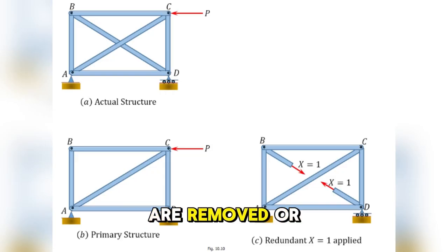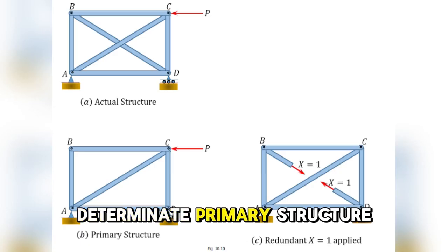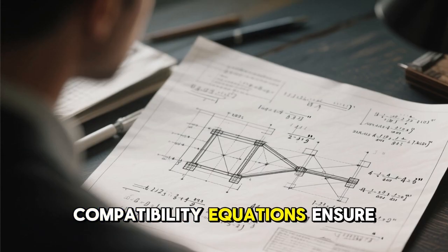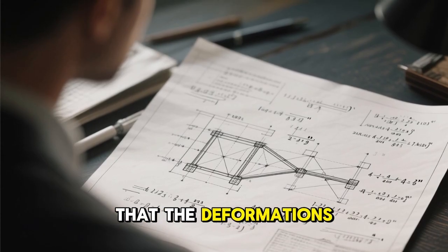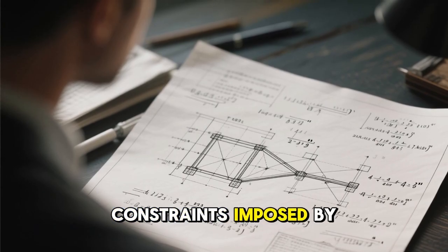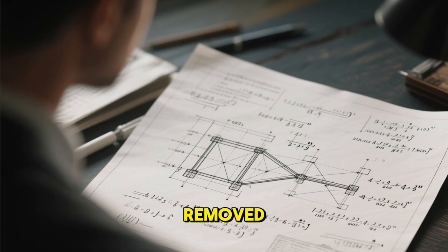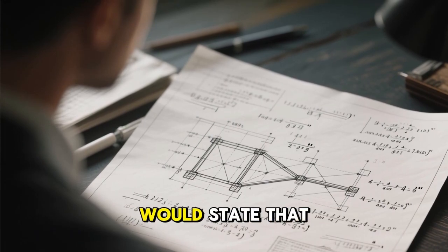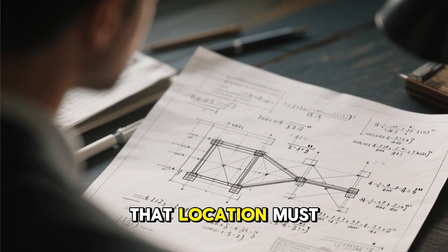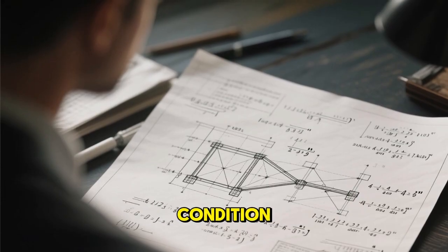The redundant forces are removed or released, transforming the indeterminate structure into a determinate primary structure. Compatibility equations ensure that the deformations in the original structure are consistent with the constraints imposed by the redundant forces. For instance, if a support is removed, a compatibility equation would state that the displacement at that location must be 0 or consistent with the original support condition.